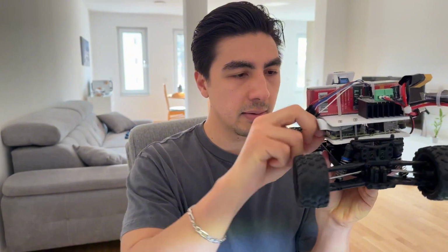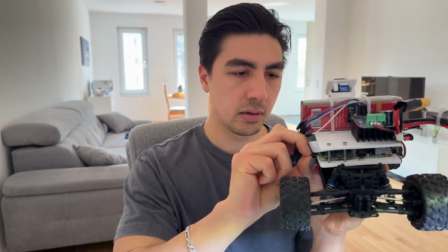So let me go ahead and try to get the SD card over here. Luckily, I put it very accessible here so I can easily take it. There you go. And it should be as simple as just putting this SD card here on the Raspberry Pi 5 and then trying to run the same thing again. So I'm just gonna get my Raspberry Pi and connect the power over the USB-C port. The LEDs are blinking already, and now let's see if we can connect to that over SSH.